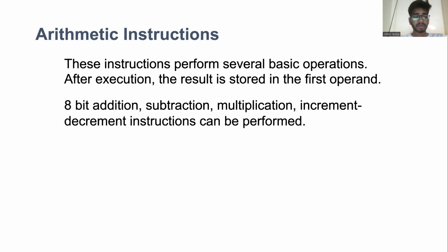And when coming to 8051 registers, there are two types of registers: 8-bit registers and 16-bit registers. 8-bit registers are accumulator register A and register B, register banks, program status word PSW, and stack pointer SP. While 16-bit registers are program counter PC and data pointer DPTR.